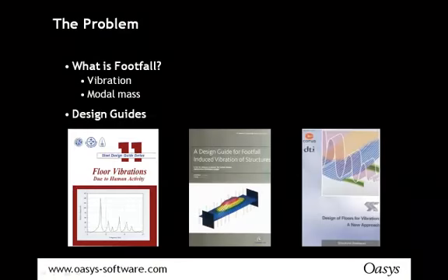Now, to help you assess the footfall vibrations, there are a number of design guides out there. One of the first was the American Institute of Steel Construction's guide, which came out about 15 years ago, I think now. Then there was the Arup method, which was published by the Concrete Centre in their design guide for footfall induced vibration of structures. That covers all types of materials. And then soon after that, the Steel Construction Institute published their guide as well, and there was a recent revision to that, which is covered in the GSA software.